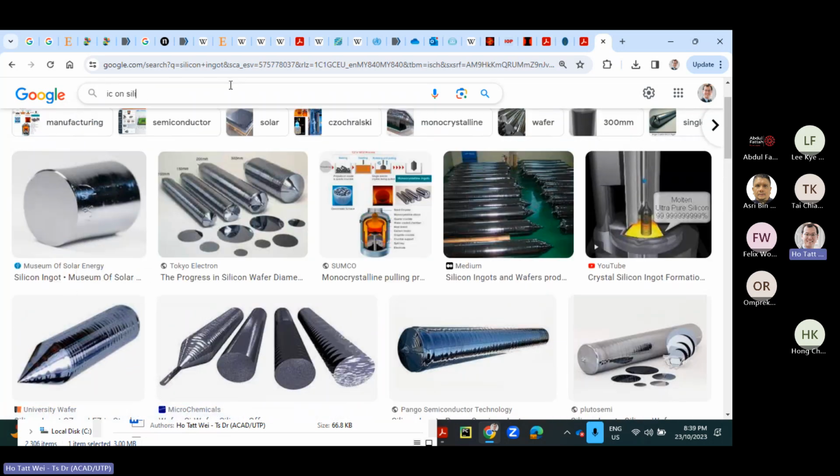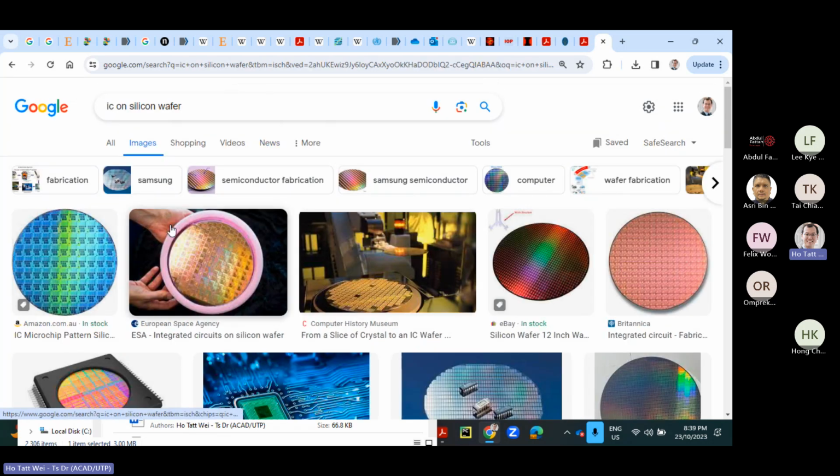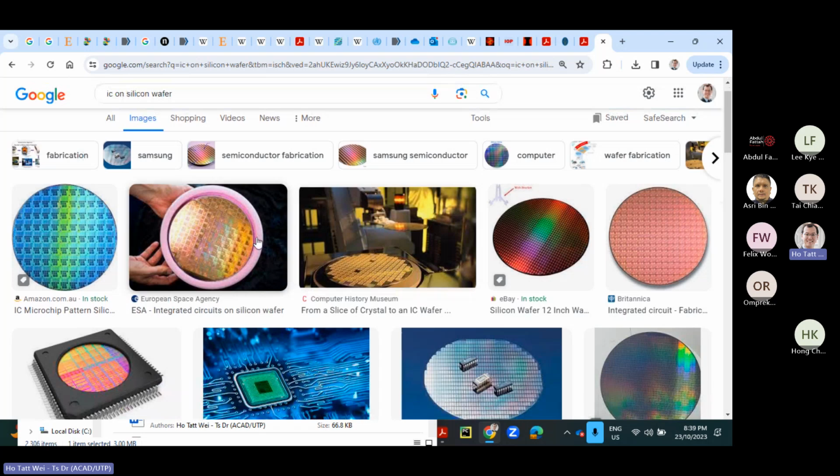I see on silicon wafer. So the wafer can be big, right? There's 8-inch, 12-inch, and 15-inch and things like that. So you see a lot of this repetitive pattern because these are all the transistors and their wires already fabricated, or already done the photolithography. But you have many, many chips. Maybe in this wafer, you might have 1,000 chips and things like that. And what happens is this wafer will be diced. After the fabrication, they'll be cut. All these things will be cut, right? And then the edge ones that are incomplete, they just throw them away. Okay. So you have variation from wafer to wafer.